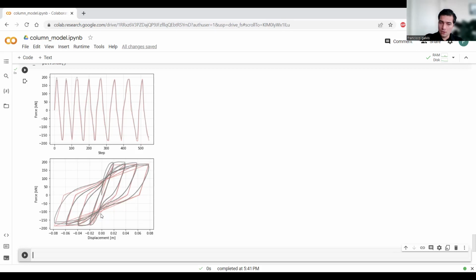We could have a more complex model that, instead of linear segments, has a smoother plastic hinge, but that will include additional parameters. So it's always a trade-off when you need to choose how many parameters you are willing to calibrate, with the uncertainty that comes with them, what type of model you would like to use, and how closely you want to replicate the results of your test. This type of model will never be able to capture this part well.